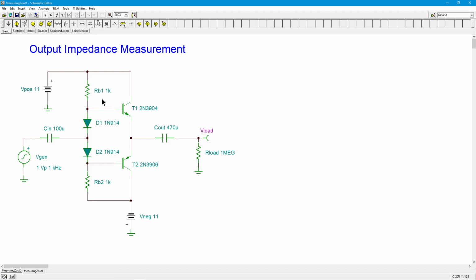This is in the section on the Class A and Class B power amplifiers. But this is how you would do it in lab, right? You would get out your scope, typically, unless you happen to have a wide band AC RMS reading millivolt meter. You might have one kicking around, but if all you have is an inexpensive little DMM, and then, like I said, it dies at a few hundred hertz, maybe 1 kilohertz, you're not going to be able to do a check for your input impedance at 10 kilohertz or something like that. But a scope, absolutely no problem.